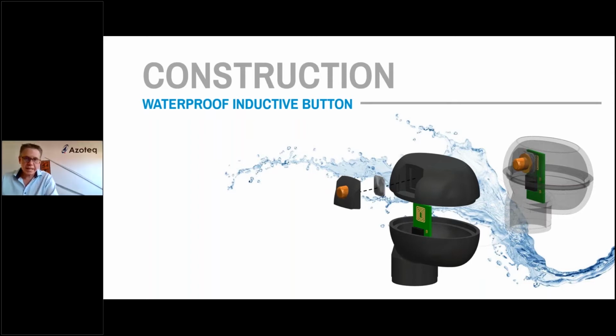So automatically the advantages for waterproofing are apparent here. The housing can be sonically welded or glued closed, fully hermetically sealed. The moving part on the outside can be exposed to water or dirt or dust or corrosion, and it will not have any detrimental effect on the performance of the inductive sensing.